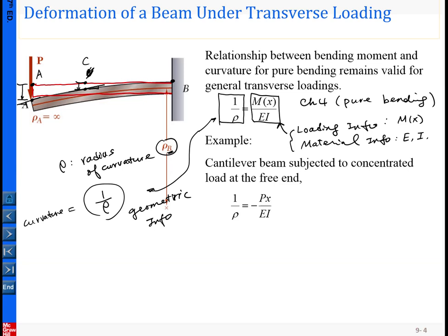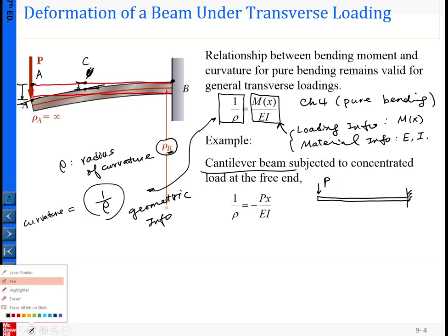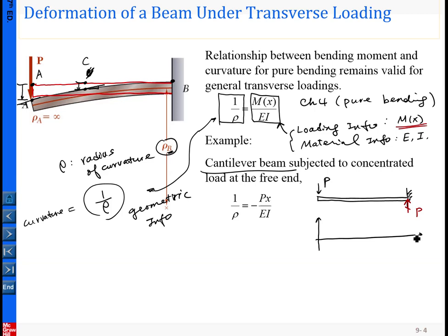And for example, here we consider a cantilever beam, and just for this case, let me see how we can do it. Basically, for the cantilever beam, let me redo things here. This is the beam, under the point load P. Here we can try to draw the shear and bending moment diagram to see how we can dig out the loading information. The first step is to find the reaction here, that's P. Now with that information ready, we can begin to draw the shear and bending moment diagram.